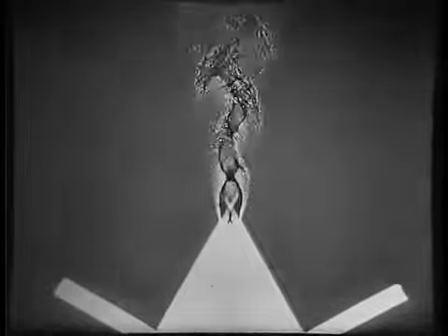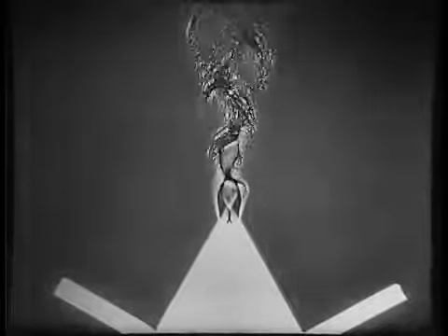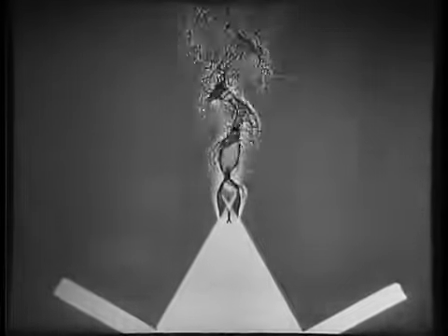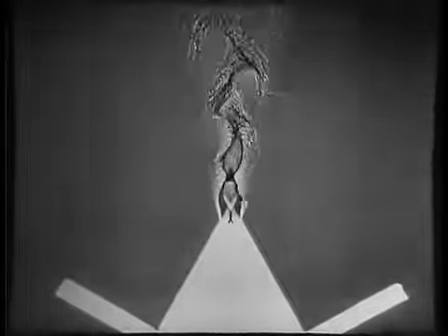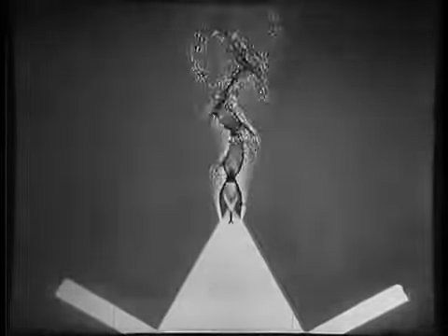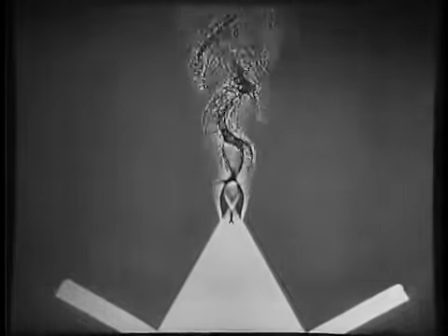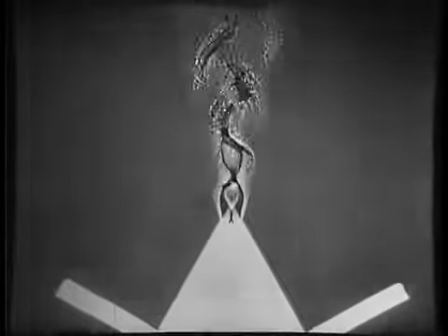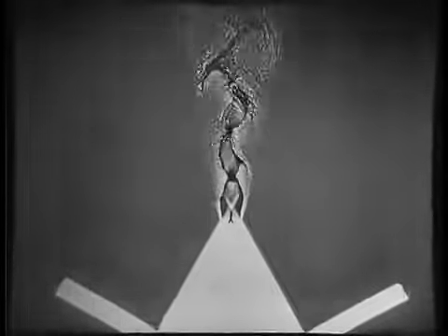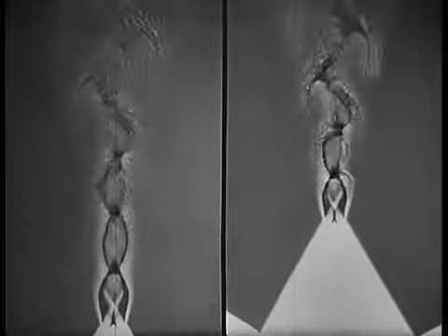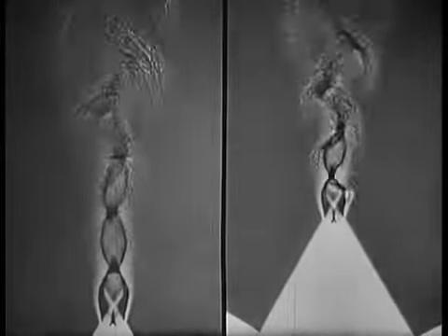First, though the frequency is nearly the same, the oscillation is much more intense. Secondly, the source of sound shifted towards the nozzle. And thirdly, vortices spring up on each side of the jet close to the nozzle and are carried downstream in the boundary layer. We now show the two films again, one without reflectors, the other with reflectors.